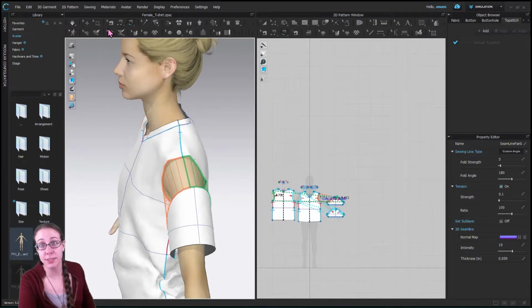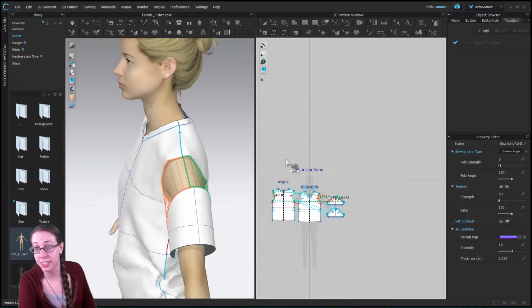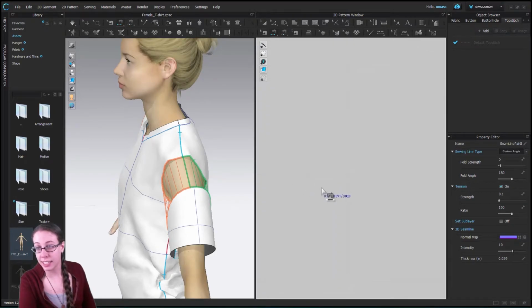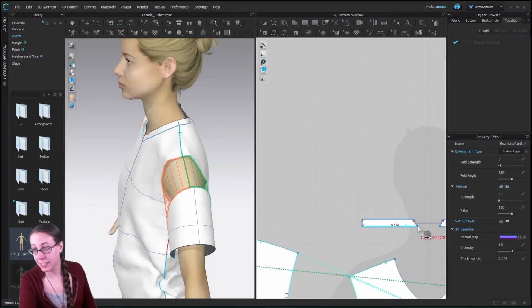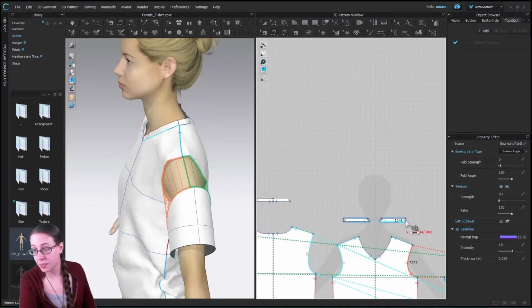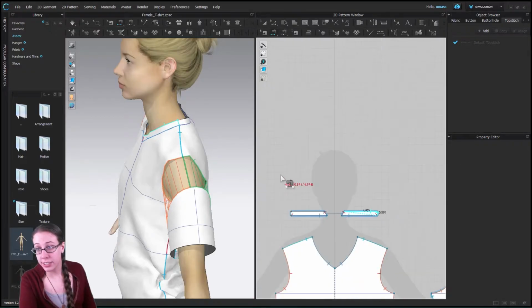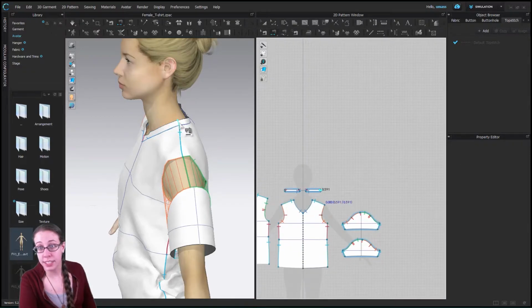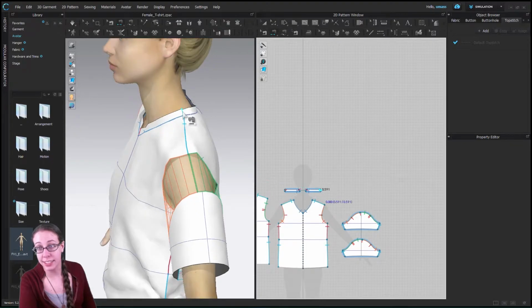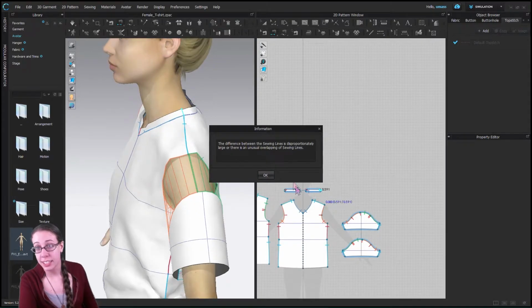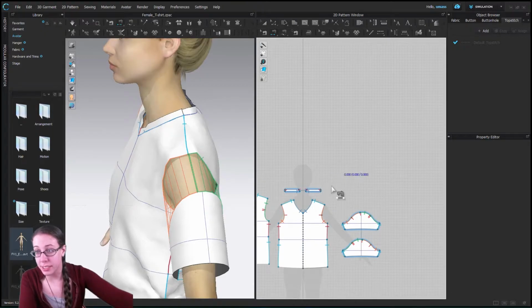together. So I am going to grab the segment sewing tool for that, and I will click on a collar edge. I want to try to get the collar edge on this side. Click on a collar edge, and then I'm going to come in here and click on the other collar edge, essentially. Maybe I clicked on the same one twice.